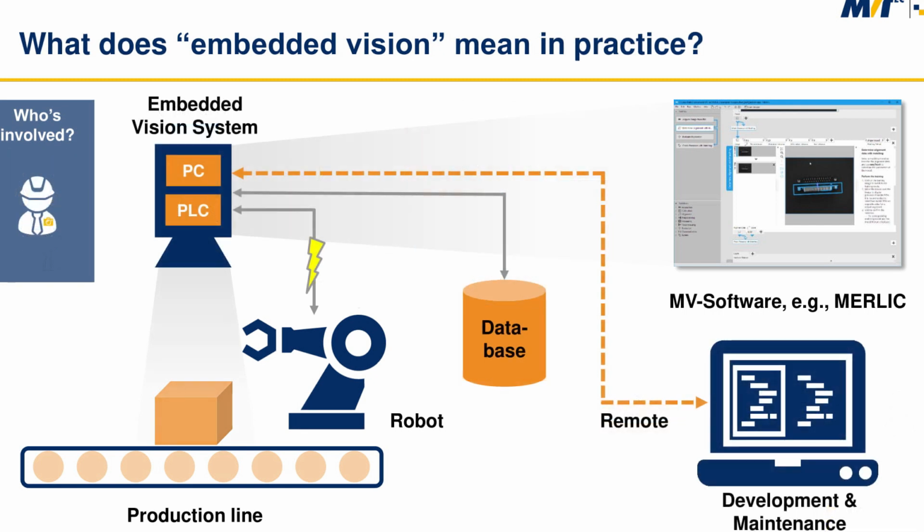So this is the reason why you can use one approach here: to use only a smart camera with an integrated soft PLC or IOs to give information directly to the robot. The main advantage is you do not need any more cabinet, you do not have a PC. This is reducing the cost and the effort for this kind of application. You reduce the interfaces because the calculation of the image, or the image processing, is running directly on the system.